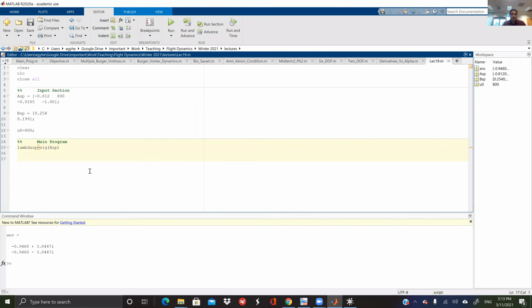So how do we do that? Well, it's a very nice command. It's called place. No, pole placement. So we really place the poles. Give me the A matrix, please. Give me the B matrix, please. And look at the help here. It's A and B and P. What's this last? P is the desired locations of the poles. So I need something here before that, the P desired.